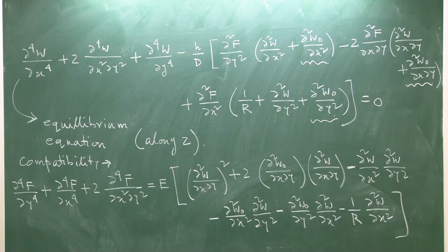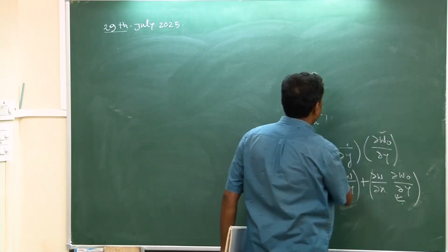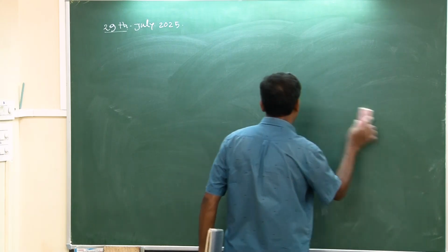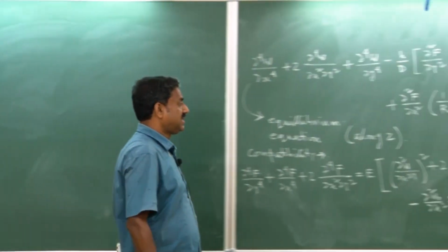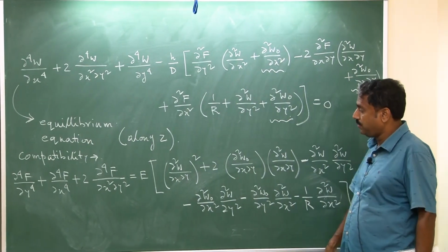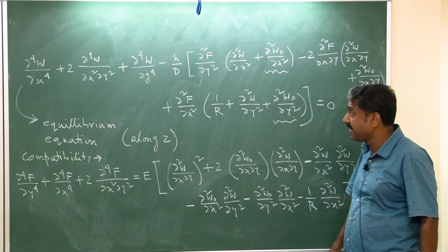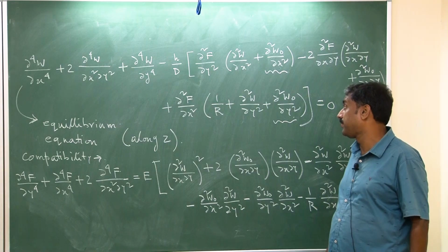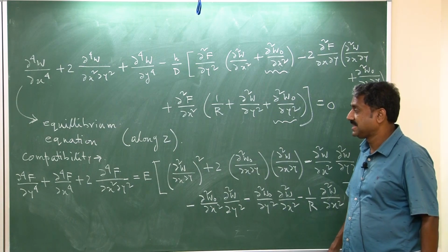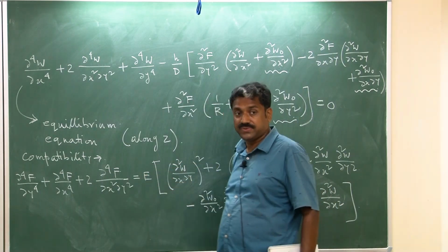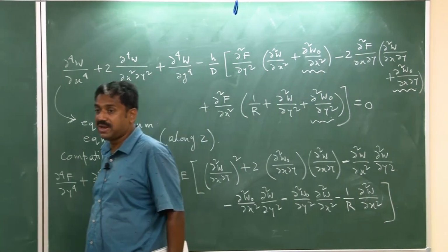Now, you can clearly see the nonlinearity. Of course, other than the von Karman nonlinearity, we are not considering all the terms in the large strain, but they are of course available. So, these two equations are a little big, complicated, nonlinear equations, and they allow the redistribution of the in-plane forces. Of course, Nxx can be derived from the second derivative of the stress function, right. So, we have to solve it, right.